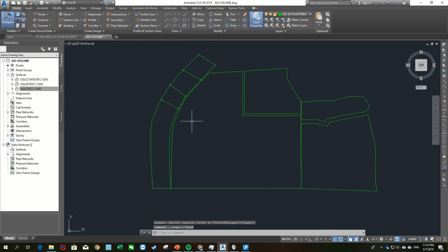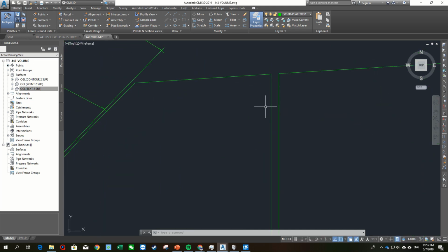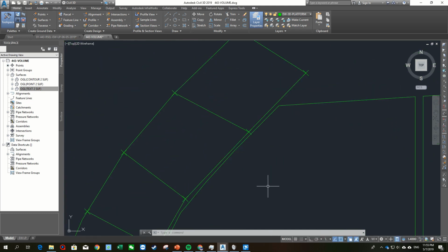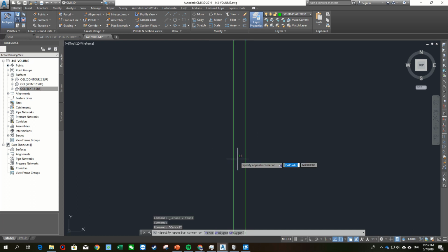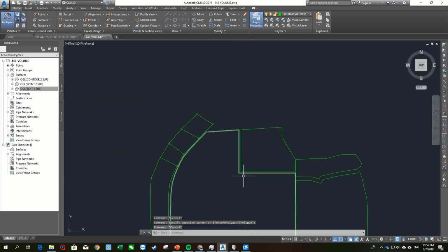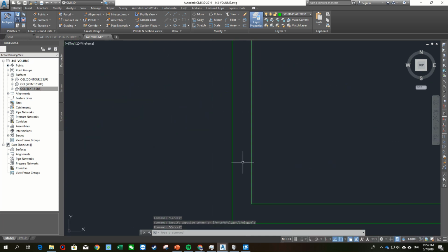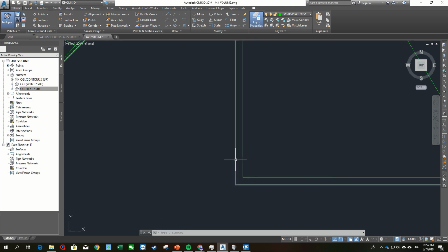First, after you draw all the polylines, you have to make sure there is some space between these two different platforms. This is because AutoCAD will automatically generate one slope for these two levels. Says this 65, this is 63.5. This is a different level. AutoCAD will automatically generate the slope for that. They will directly match the slopes.